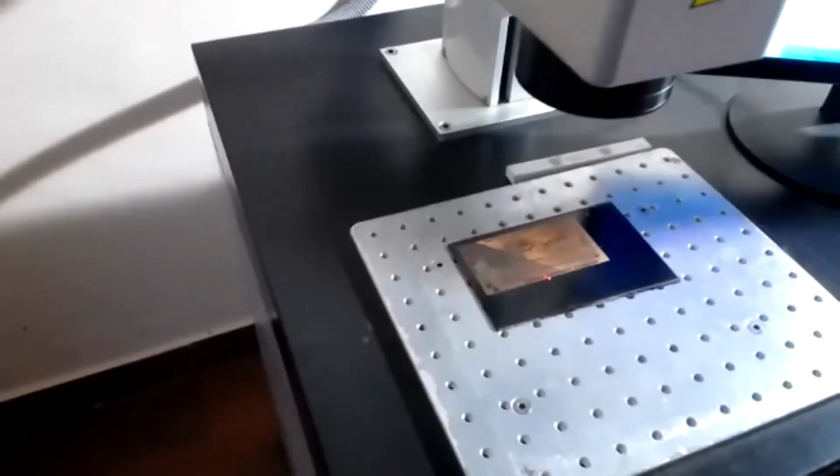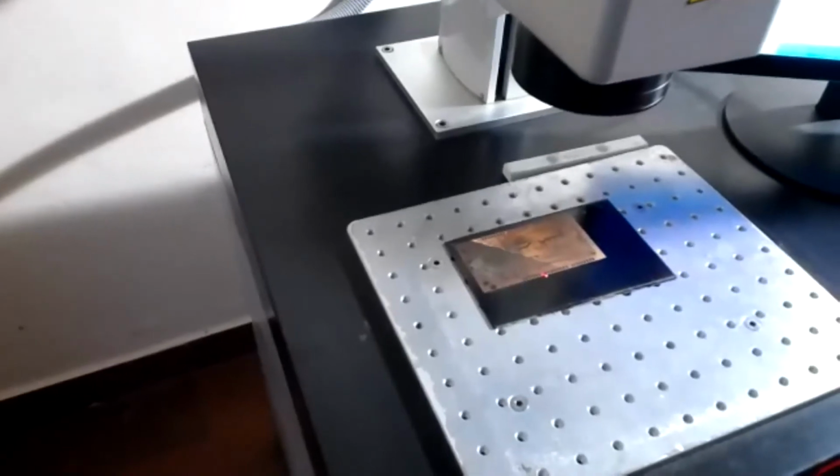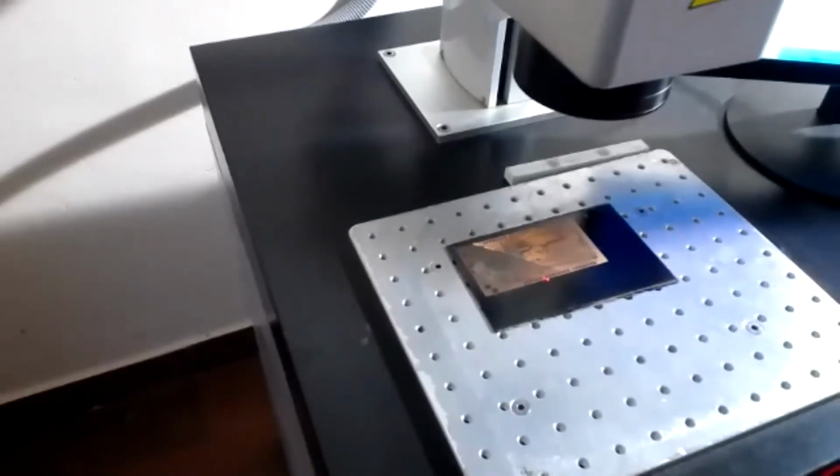Secondly, you can ask why we didn't go for the UV exposure method. Yes, the UV exposure method is very good, but when you go for it, you need to prepare a negative film. For negative film, it is very difficult to get good printing, because when the circuit is small, or whenever the circuit spaces are big with a huge number of gaps, things are very easy. But when the spaces between the traces are very small,